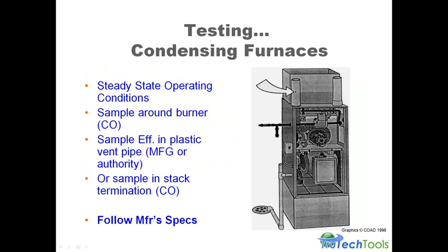And if you run across that situation, get a heating contractor out to do the testing with you, because leaving an appliance untested is just negligent. So you really need to get that thing tested. And typically what I'll do is drill and tap the flue pipe and put a 3/8 brass plug in there, and screw a plug right into the PVC. Pipe plugs are tapered, so it'll go in and seal just fine. And really, you can drill a hole and you can just tap the plug right in. The brass plug will self-thread right into the PVC.